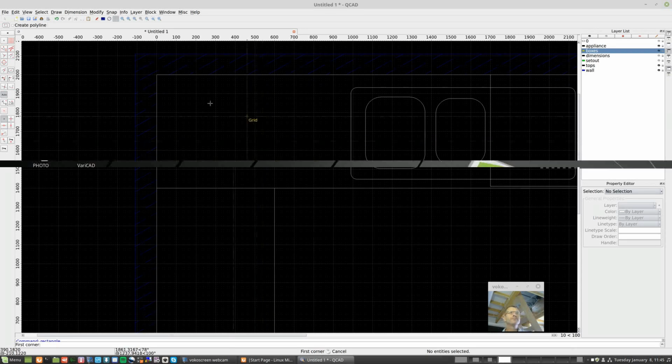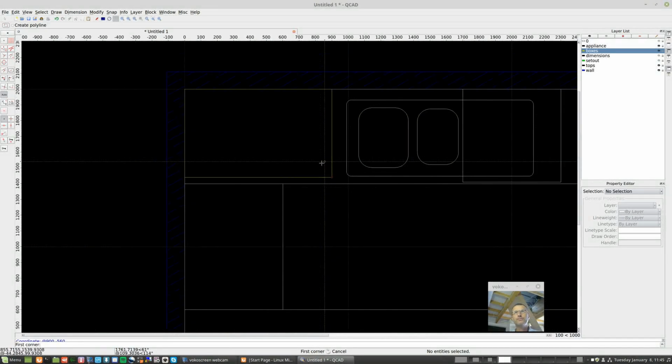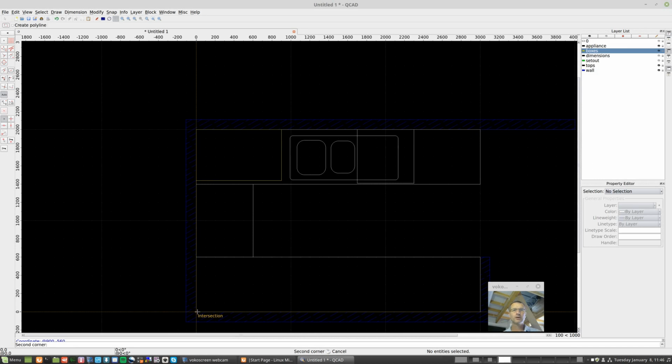Okay, right, so what is a common thing to do is space at, I don't know, 900, comma, minus 560. Now the boxes are smaller than the bench tops because you have an overhang, you have a door thickness and so forth. Okay, so what have I just done? Okay, so there's that box, which is okay. Now we'll do the same over here, but I'm going to do something different on this side. Space at 1100, comma, 560.